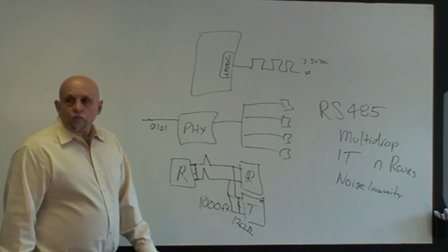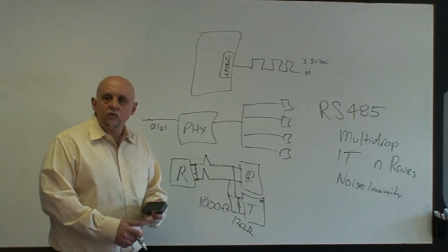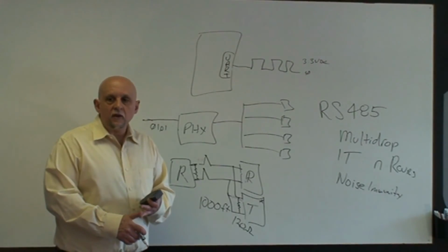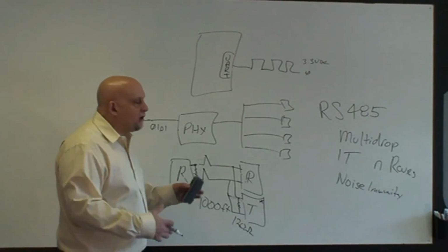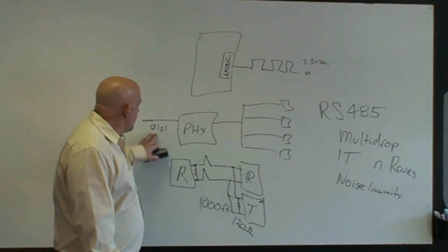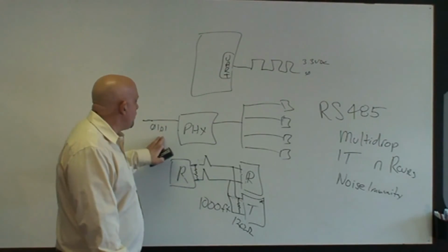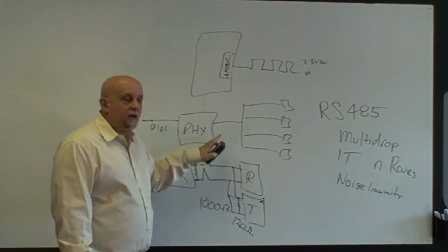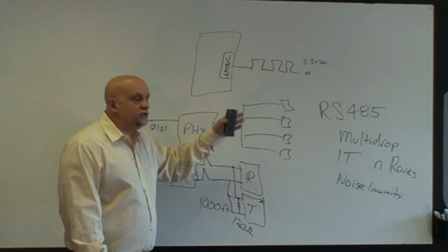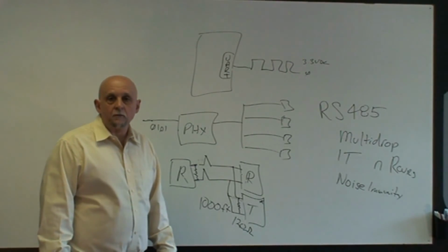So that's the difference between full and half duplex. This is half duplex communications. RS232 was full duplex communications, and I think that takes care of my brief explanation of RS232 and 485, and how we go from bits that are generally 0 to 3.3 volts at the processor voltage level, to drivers that send out data on 232 and 485, on those various kinds of serial networks like Modbus.